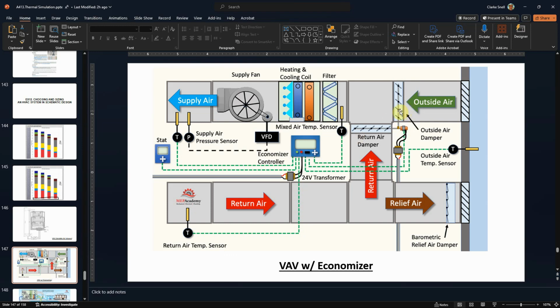If we have dampers, which can restrict the flow of air, and they're electronically controlled so that we can open and close them based on the outdoor temperature, or open them a certain percentage, then we can bring in more fresh air when the temperature outside is conducive to, for example, cooling. In large buildings, sometimes you're cooling even when it's cold outside. We bring in outdoor air, turn off the heating and cooling system, and just cool with the outdoor air, so we save energy.